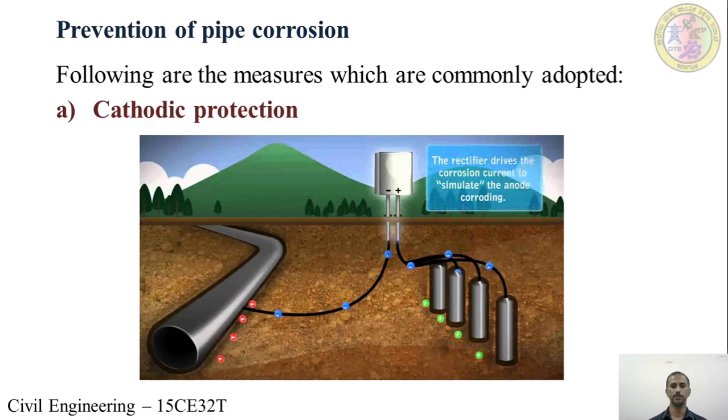This causes lower electrical potential of the pipe, making all the electrons from the surroundings move towards the pipe material and thereby preventing the Fe2+ ions from migrating from the pipe. This cathodic protection can also be done by making the pipe in contact with anode metals such as magnesium, creating an electrical potential difference between them and making the electrons flow from anode to cathodic pipe.